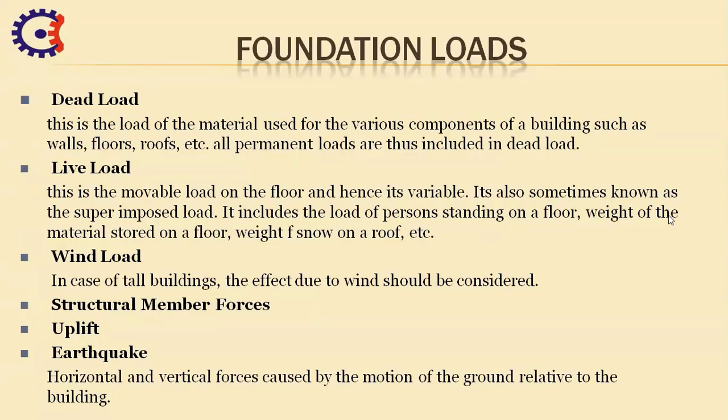The type of foundation soil must be taken into consideration in the evaluation of the design criteria. The horizontal earthquake forces in alluvial ground should be taken as not less than 3 times those on rock, because alluvial soil and soft ground tend to amplify shaking.